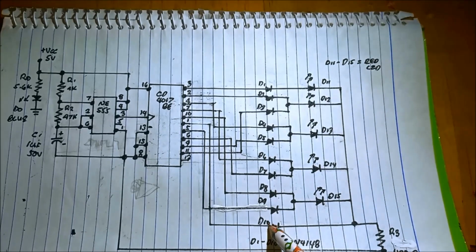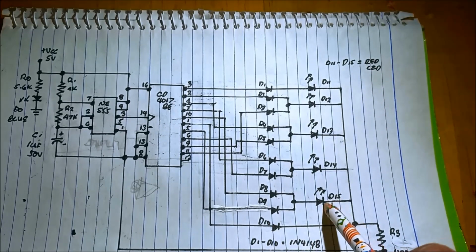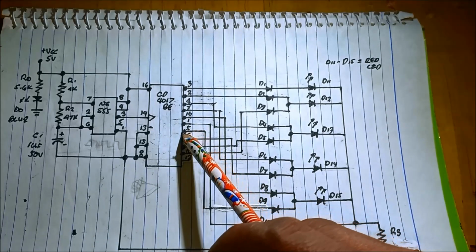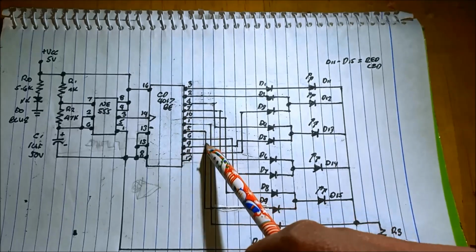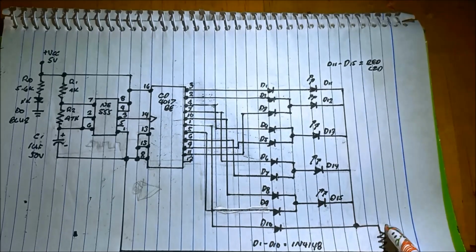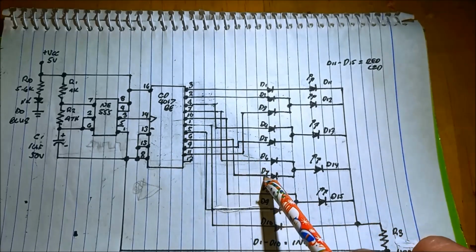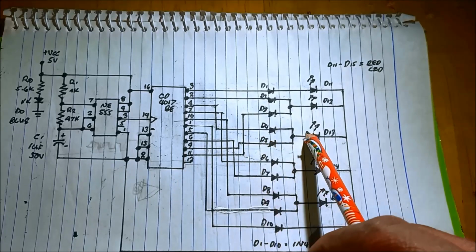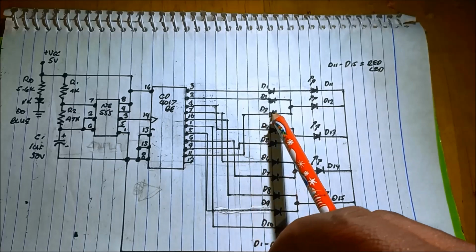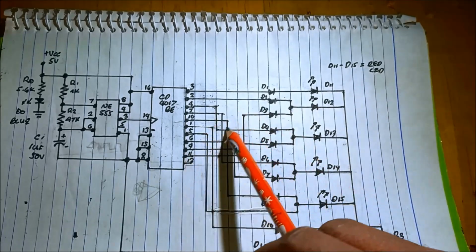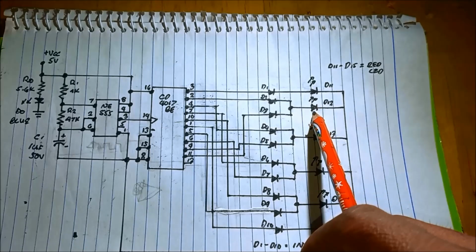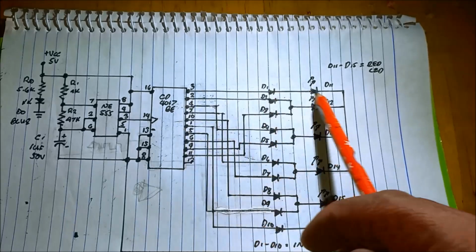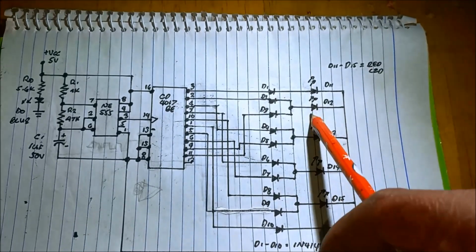And then since it is bouncing back, we need to turn on this D15, and the sequence, since it is continuously turning on the LED by the sequence of the number, pin number 5 to the D4 to the D15 to the ground, pin number 6, D7, D14 to the ground, pin number 9, D5, D13 to the ground, pin number 11, D3, D12 to the ground. Again, it will go back to the pin number 3, continuously bouncing back the LED.